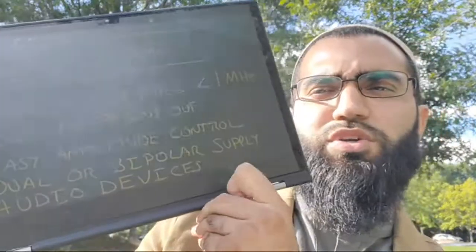In the next case, I mentioned easy amplitude control. Also, you can use a dual or bipolar power supply, meaning that you can have positive and negative voltage supplied to your op amp. Therefore, you'll be able to swing your output voltage both positive and negative, or you can only supply a positive voltage and ground the other terminal or power supply end of your op amp.